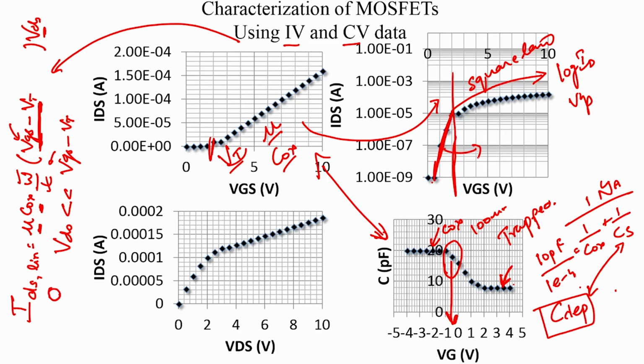Here you can see that even though there are few data points, it is an almost linear dependence, and we can now calculate the subthreshold swing of the MOSFET. And what is the subthreshold swing? It is the volts per decade. So, what was the gate voltage required for the MOSFET to travel 1 decade up in current?